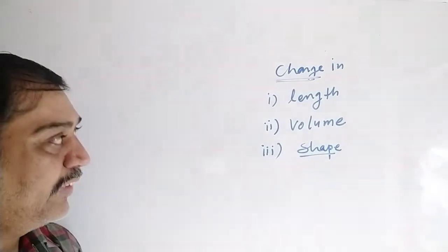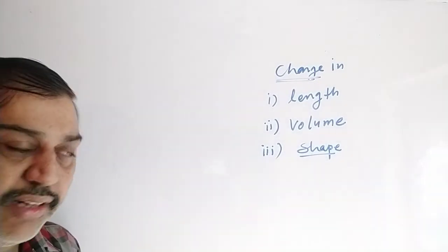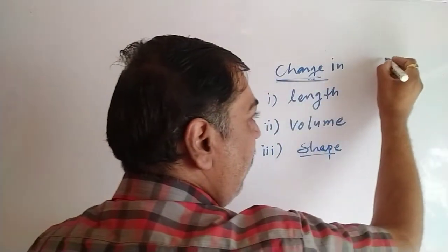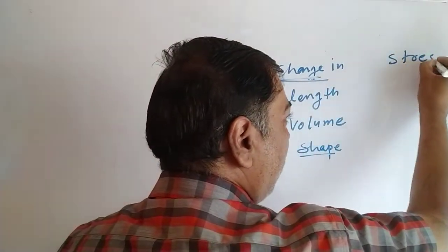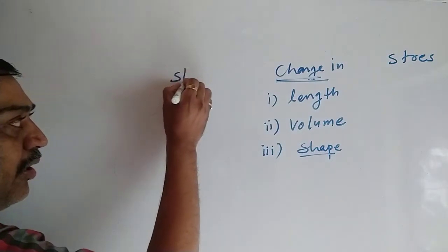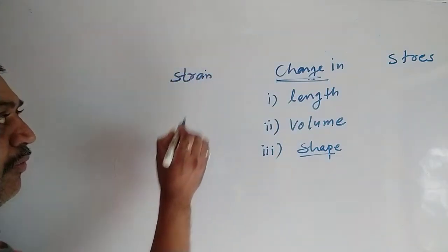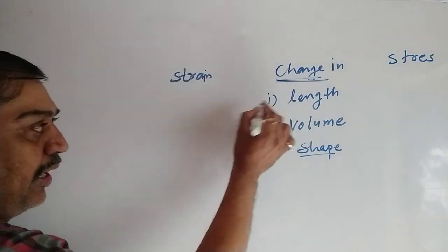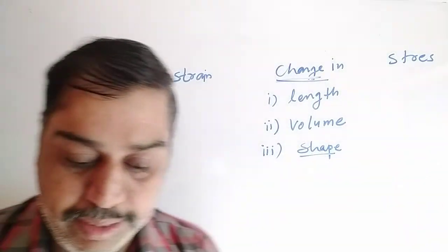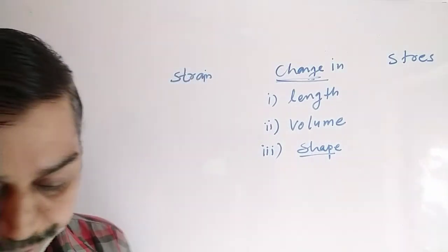So see, whenever there is a change in length, I will write here the type of stress and here the type of strain. Whenever there is a change in the length, the stress is said to be tensile stress or longitudinal stress.